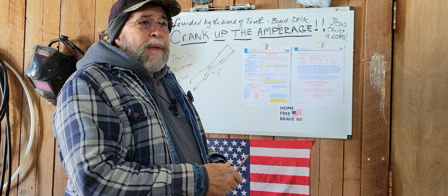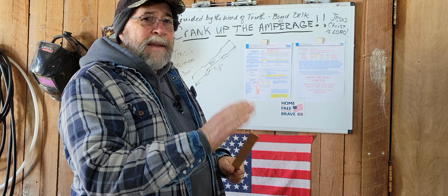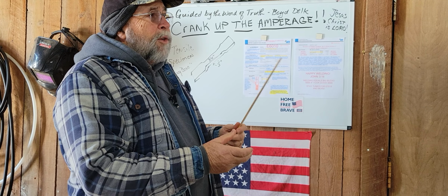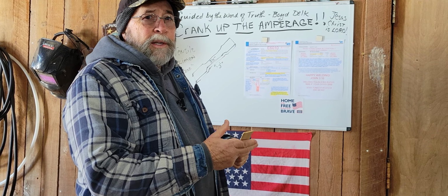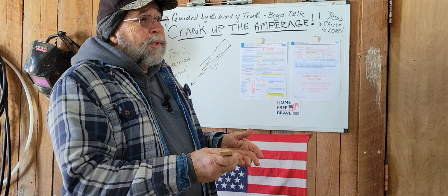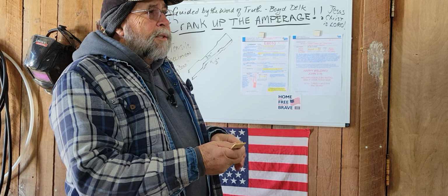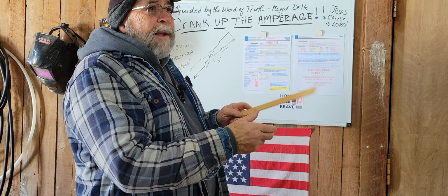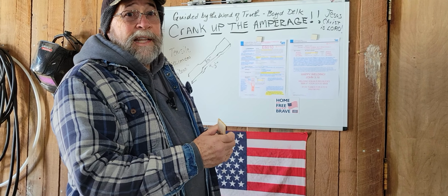So what I did from that point on was I just started cleaning everything up real good with a flapper wheel. I had a knife edge on it. I put my 1/8 wire in there to establish my gap. I used the 6010 rod, of course, and I turned the arc force, or the dig, up to +2. Turned my amperage down to, I don't remember, this is going to sound cold to you, 60 or 65, which is what the arc force does. It helps you maintain the arc, and be able to slow down and watch the puddle as you're welding. So that's what I did. And the root passes, even on a knife edge, were going in there slick.